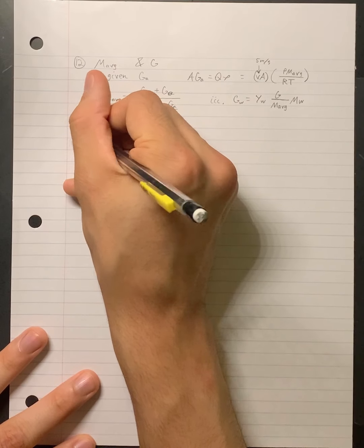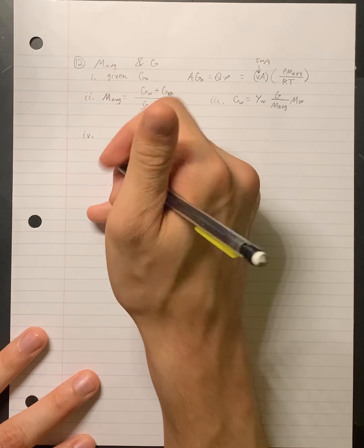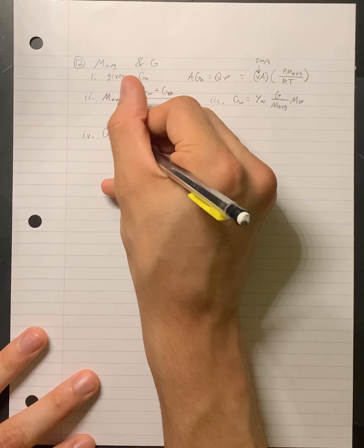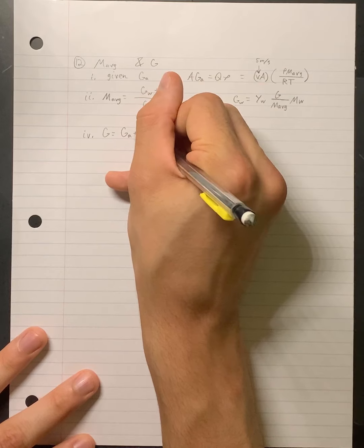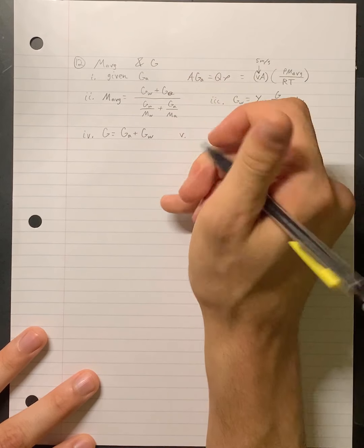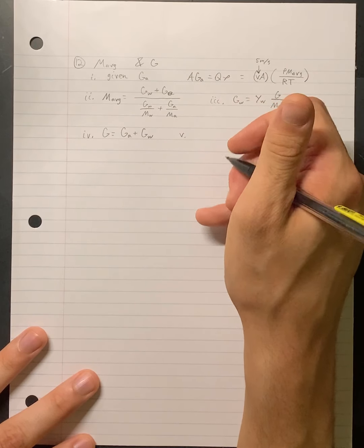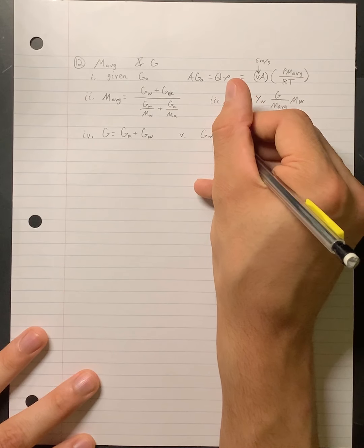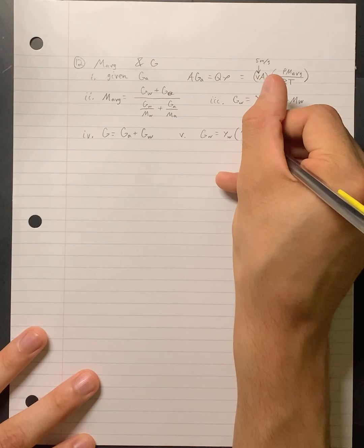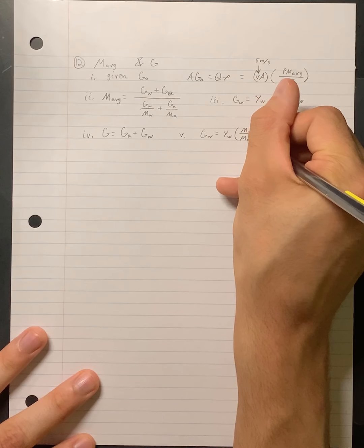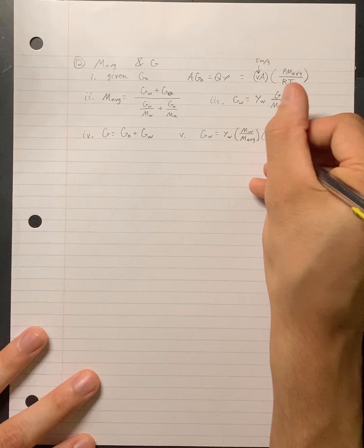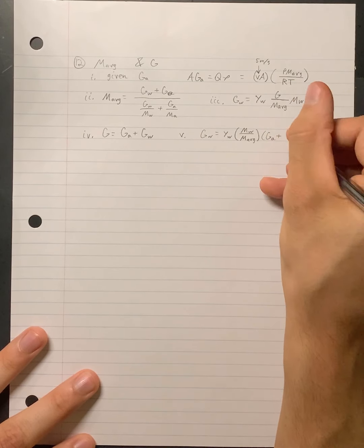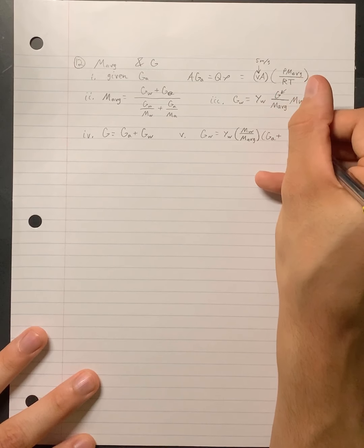Now that we know that, we can derive a few more statements. Actually, before even we had that, we've got the overall mass flow rate has to equal the air plus the water. Now with that, we can transform that equation before that. The mass flow rate of water equals mole fraction of water times molecular weight of water over the molecular weight average. Then plus those two quantities there, because we're simply replacing this guy with this guy.